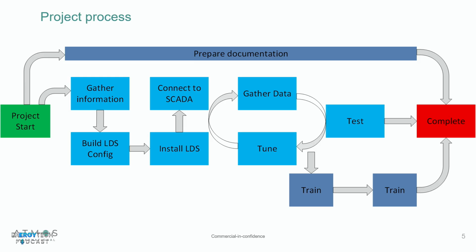And then also they rush to do the testing. So they want to do the FAT before the pipeline even runs. So we put together simulated data for that. And of course, you don't see data faults or instrument peculiarities in it, which are some of the main things that you're tuning for. So you don't have a real tune. And then what happens is the test data is just not very good because you're not really testing the system, and you have to change it a lot when you start to get real data. So I would say it's not very effective to do a project that way.